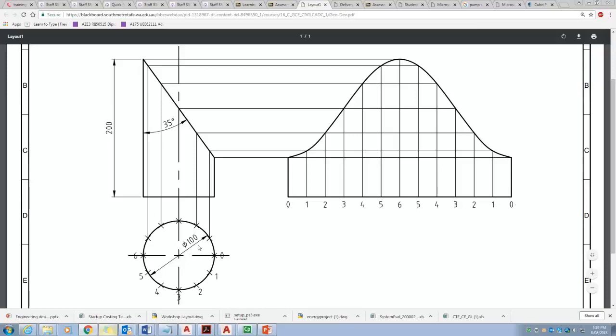So if you look at it, 100 there, the perimeter or circumference of the circle will be 100 multiplied by pi, which is basically 3.14, so that will give you 314.15. 314.15 by 200 is the minimum rectangular sheet required.